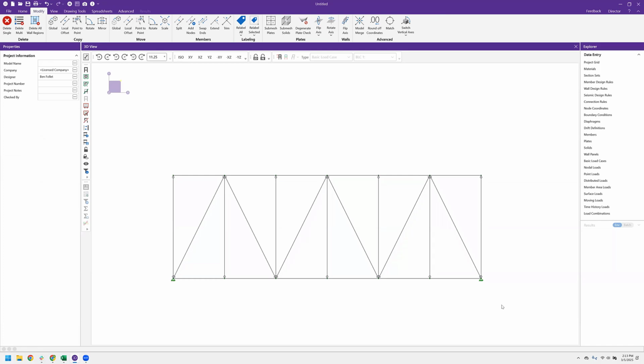I've got 2 boundary conditions. So essentially now I have everything except for my loads and the other characteristics that I could use to create this particular truss. Now, that was just modeling from scratch, right? What if I wanted to go ahead and make some changes, or maybe another way to model?